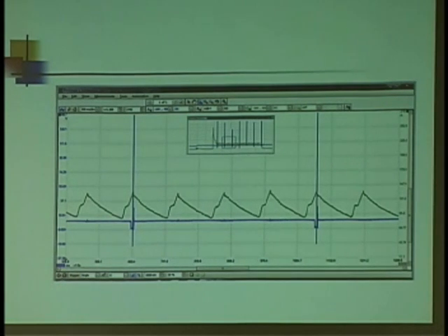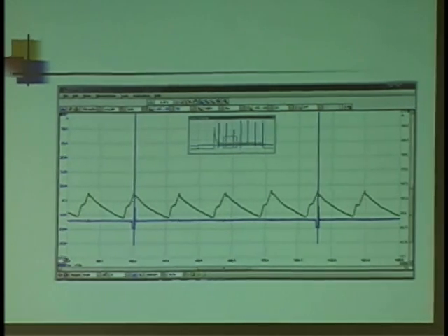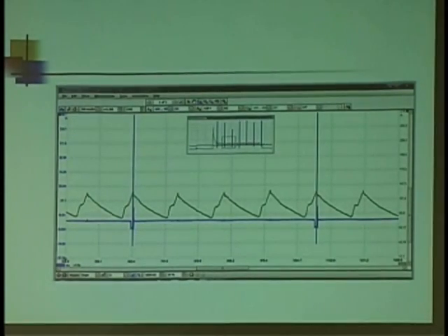But let's just zoom in and we'll take a closer look now that I have that reference point. How many cylinders do I have in this engine? 4. Is there anything else that this pattern is telling me? Remember what we referenced earlier. If the peaks are not that wide, if they're shorter than what you would expect to see, and you would suspect a low compression because of an out of time, is there anything in this pattern that would tell you the same thing?